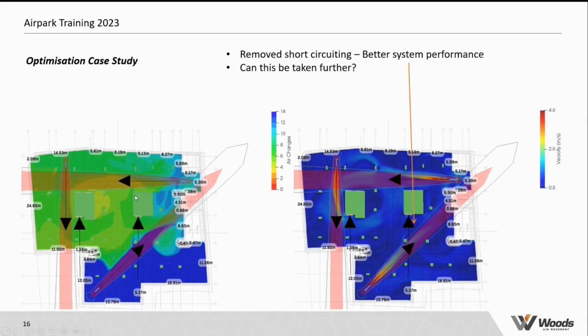So what I've done here is I've once again repositioned and re-angled this bottom jet fan, angling it more across the car park, away from the extract point to more push the air towards this side and allow then this larger jet fan, now that we've put it into the car park, to then collect the air which is in this region and draw it to it and then blow it out again.